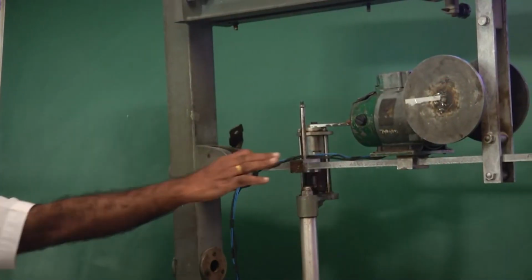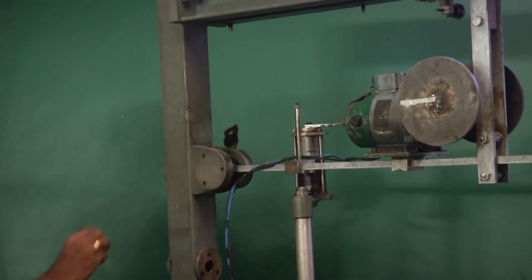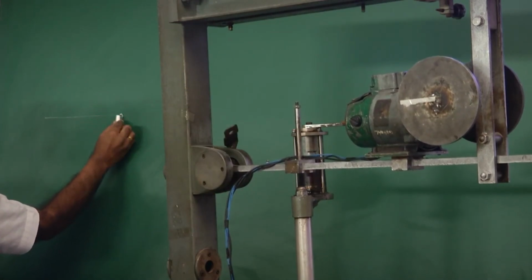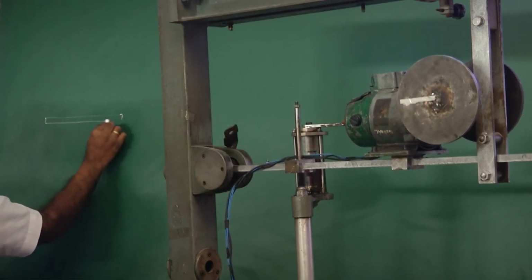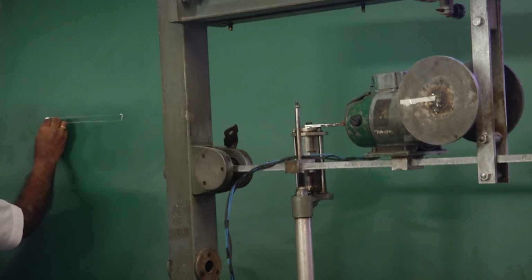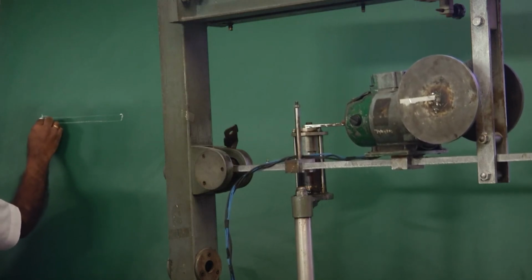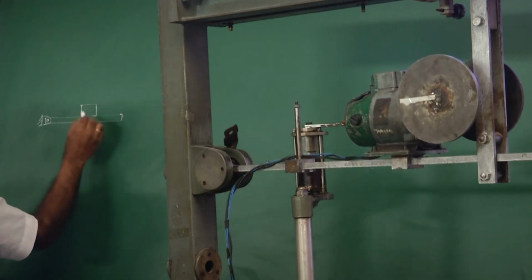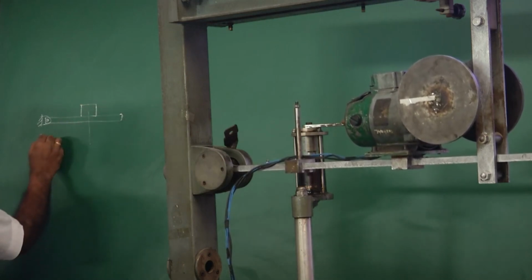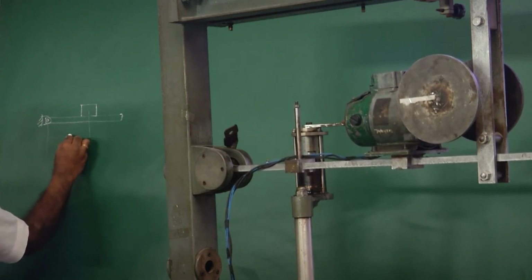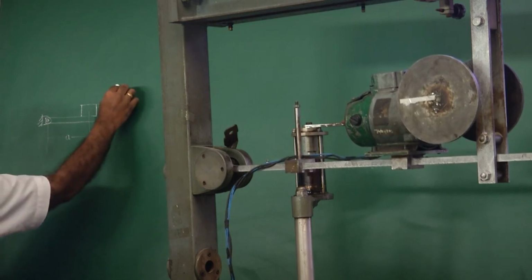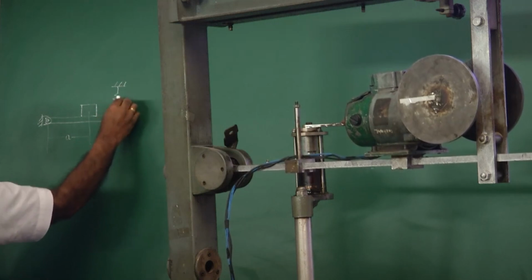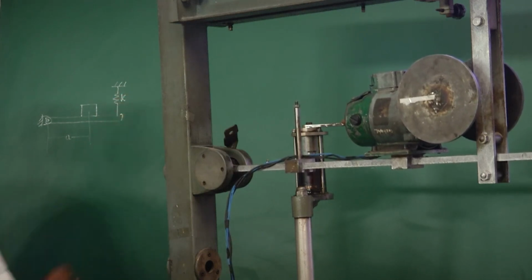So, the beam executes an angular vibration. Okay. So, this simple vibratory system I can represent by this simple beam which is hinged at one end. So, I can show it hinged here, with the mass of that motor at an appropriate location as it is given. So, maybe this distance is a, and the beam is supported at its tip by a helical coil spring. So, that I am representing as k.